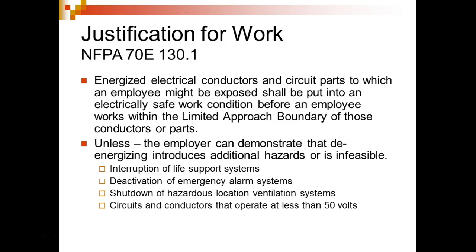So understanding that range, what you should put this meter on before you put it in the circuit, you should double check that. Verify it before you put those leads in there that you got it on the right what? Right units. When you're measuring volts, you got to put it on volts. When you're measuring resistance, you got to put it on ohms or resistance, right? When you're measuring current, you got to put it on amps.